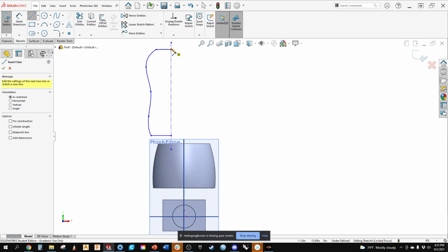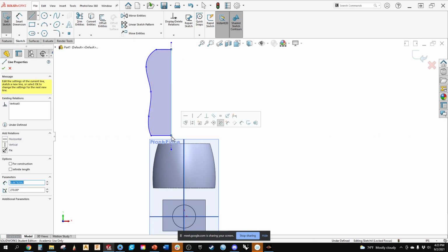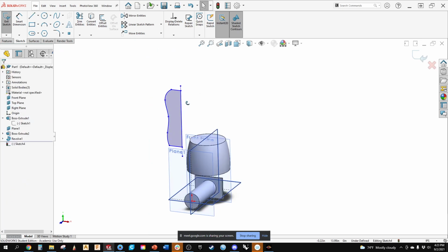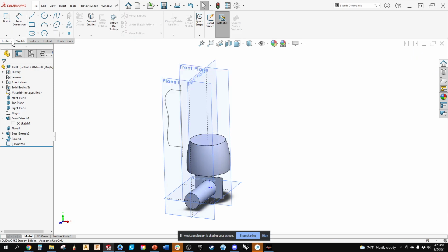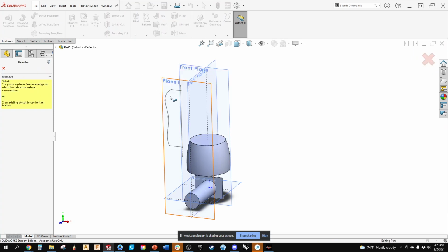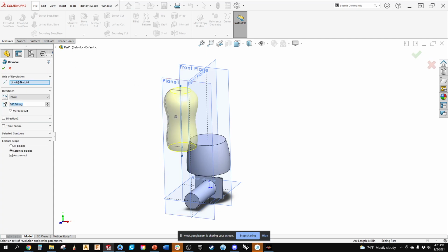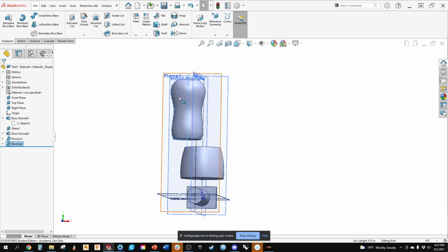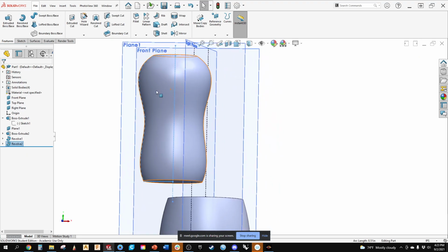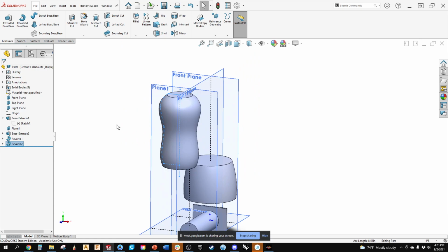Again, I want to make sure I finish that off because I want it to be a solid object. Exit out, hit our revolve. Want to make sure merge is turned off. So there you can see I can start getting much more of a sculpted surface, something that looks like you would have made on a lathe. Pretty quick, pretty simple, single line.